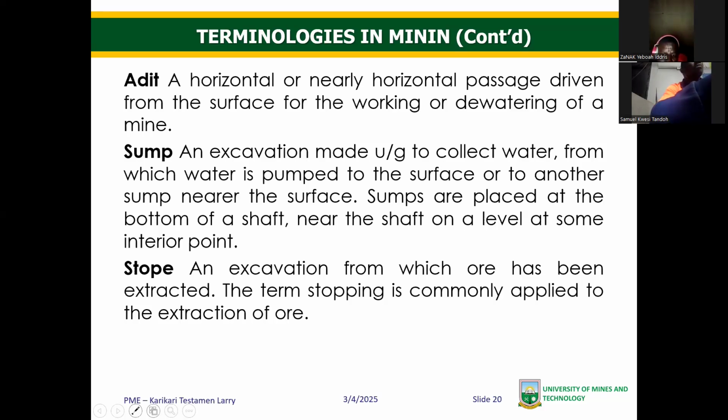So what we do is that we create, on every level, or even on surface, at every point where we are mining, a sump to temporarily take water. You pump water to a sump. The word is temporary. Then after that, you do secondary pumping. That is pumping the water from the sump outside the mine. That is what we call a sump.